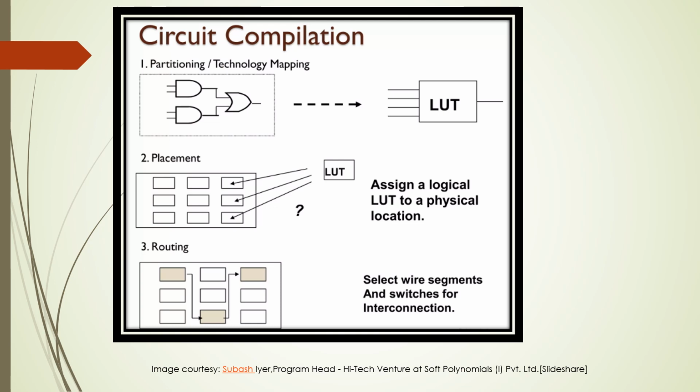Based on that, you design a lookup table with so many inputs and the output as required. Lookup tables are designed, and such lookup tables are assigned to various logic blocks. That is called placement. For partitioning, we do technology mapping, in which we develop the lookup tables and all things, flip-flops, everything. And after this, the next part is assigning these lookup tables and elements to the various configurable logic